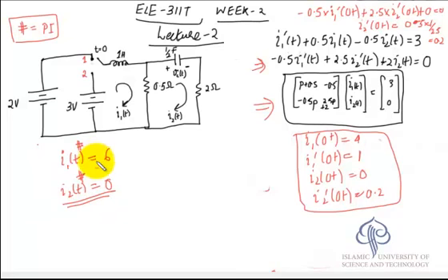The other way of doing it is to assume a constant value a, another value b, and then put in those values here. So you'll get 0.5 a minus 0.5 b is equal to 3, and then you'll get twice b is equal to 0, so b is 0, so this current is going to be 0, and 0.5 a minus 0 is equal to 3, so a is equal to 6.